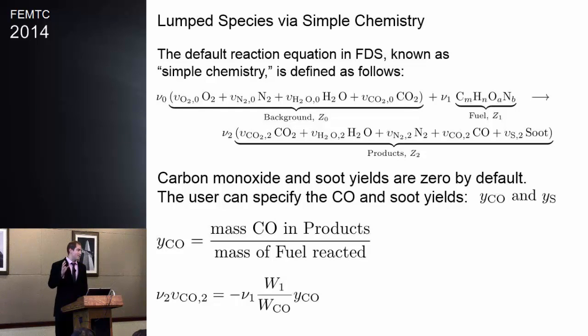And so we give you the option to run in all primitive species or in lump species. And so a lump species is really, like you see here, a combination of species that will transport together, diffuse together, and react together. And the nice thing about that is when you can lump species, it's very advantageous in the code, because the less species we have to transport, the faster the code runs. So each primitive species nominally adds about 5%, give or take, to computation time. So this allows us to maintain speed while also giving you guys a lot of options.